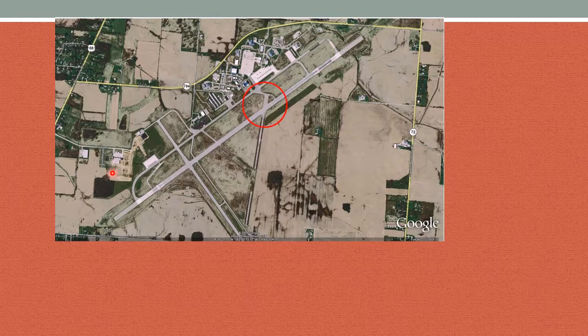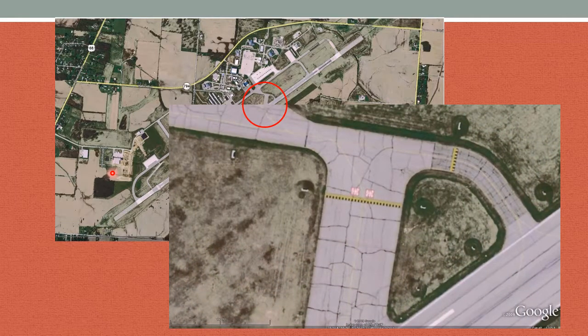Let's take this intersection here, which simply looks like an intersection of pavement. But when I use a different scale and make it larger, we can see much more information is available. Meanwhile, if I'm using an architectural scale of 1/4 inch equals 1 foot, if I draw a 12-inch object, it will be 48 inches long and much too large to fit on a page.